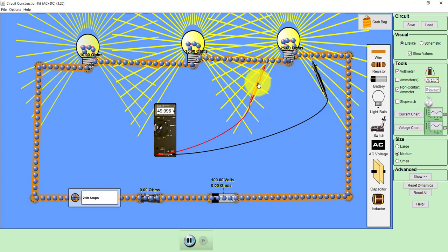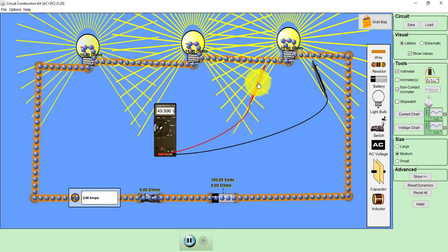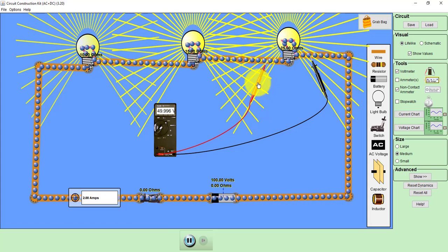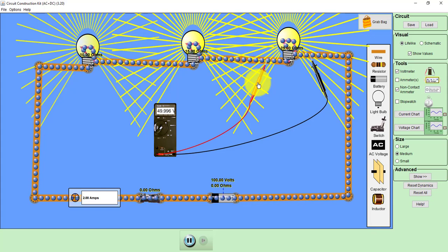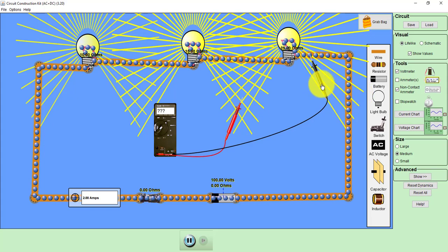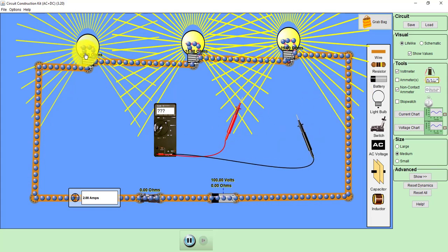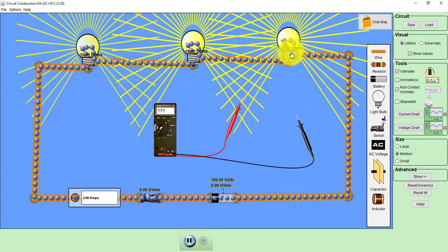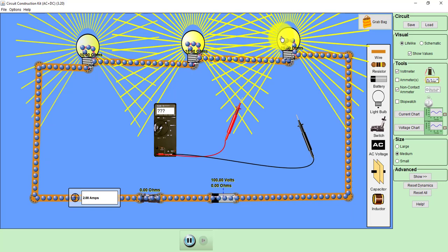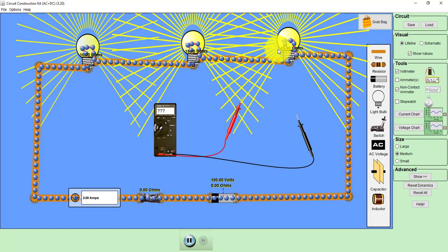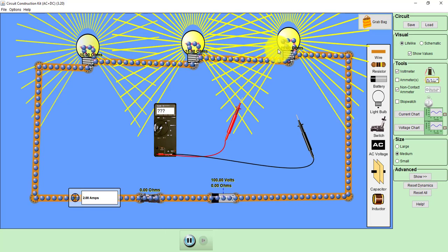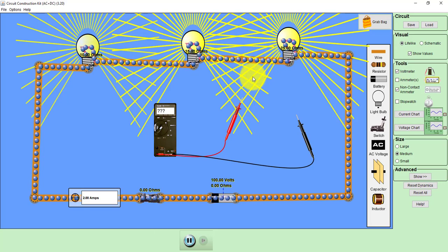Now the third characteristic says that the total equivalent resistance of a series circuit is equal to the sum of the individual resistances. Now how much is the individual resistance? 10 ohm, 15 ohm and 25 ohm. If I add these, how much will be the equivalent resistance? 10 plus 15, 25, plus 25, that is 50 ohm. So the equivalent resistance should be 50 ohm.